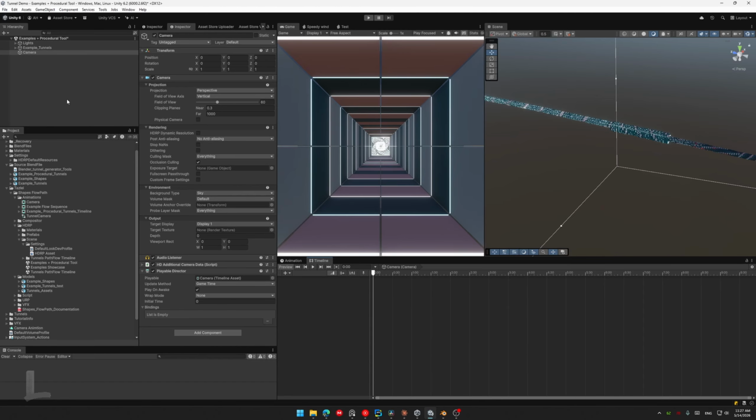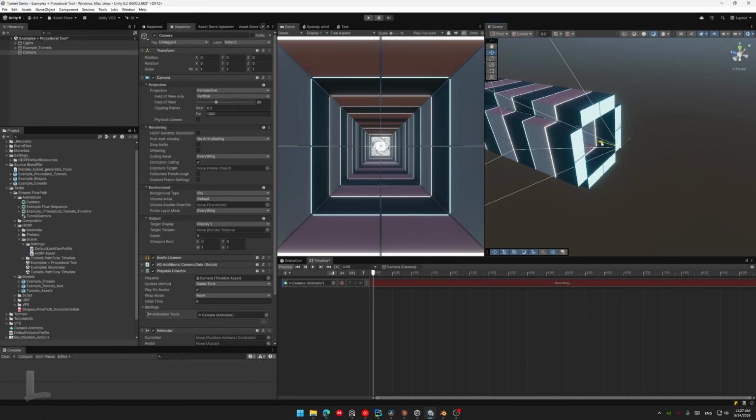To animate the camera, I'm gonna drag the camera here and create an animation track. I just need to press the record button while I know the camera is at the 0 position, to record the first frame. I'm gonna slide it like that. You can see something got detected, and knowing the blue arrow is the z-axis, I could just type a 0, so we're detecting this frame as the 0.